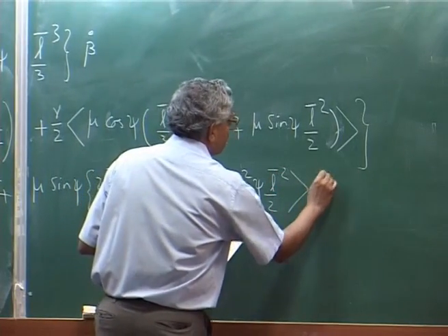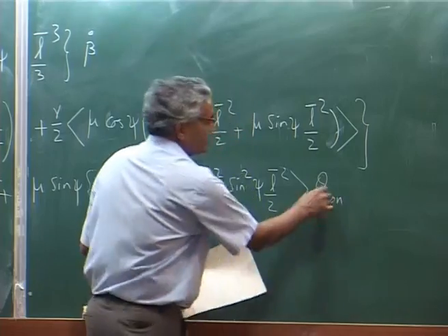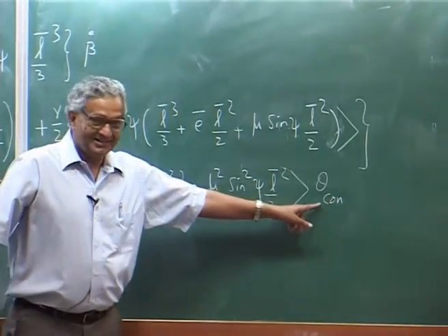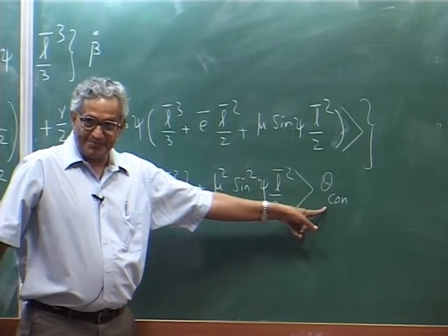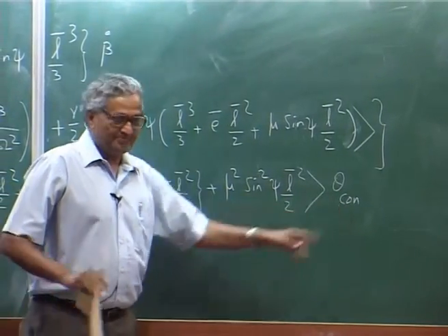This is into theta control input, that is the theta pitch input the pilot gives, theta naught plus theta 1 c cosine psi plus theta 1 s sin psi, that is this term.